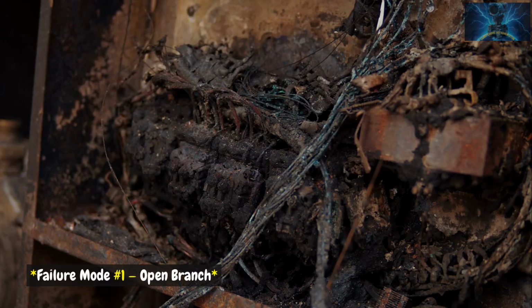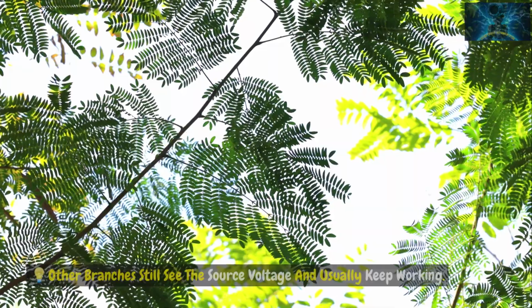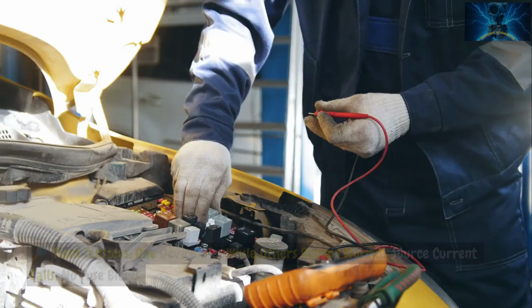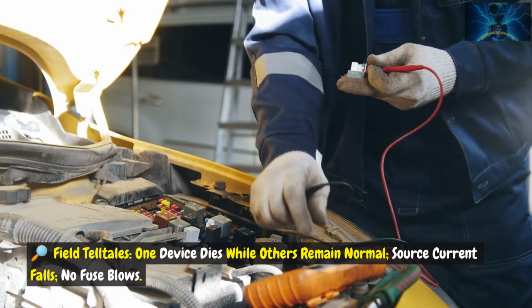Failure mode number 1. Open branch. An open branch is a broken path, so its current falls to 0. Other branches still see the source voltage and usually keep working. Result: total current drops and the equivalent resistance increases. Field telltales: one device dies while others remain normal. Source current falls. No fuse blows.